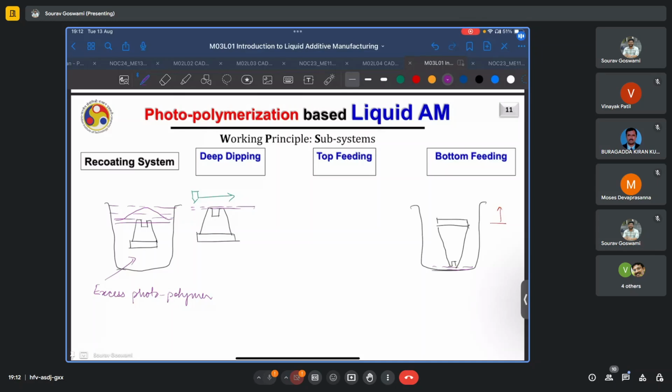Now, this can be accomplished in multiple ways. It can be accomplished via gravity, that is, we simply move the stage up by some distance and the fluid will flow into place. However, if the region is very tiny or the fluid is very viscous, it might not be possible to accomplish this on its own. So we can also use some sliding or rotating type of mechanism, and we'll take a look at this in further lectures.